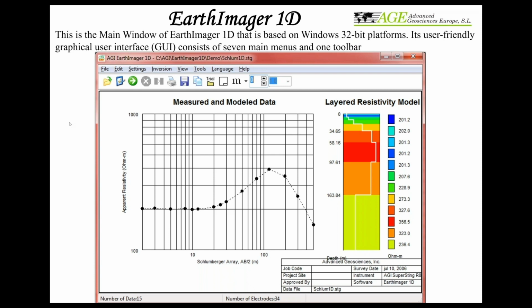In that case, you can repeat that, or our instrument is designed to automatically repeat and reduce those high voltages and then try to get the optimum data. Typically you will see an input overloaded error on our instrument. The instrument will repeat, change the automatic gain, and drop down the voltage, eliminating the saturation problem, and then you read good data.